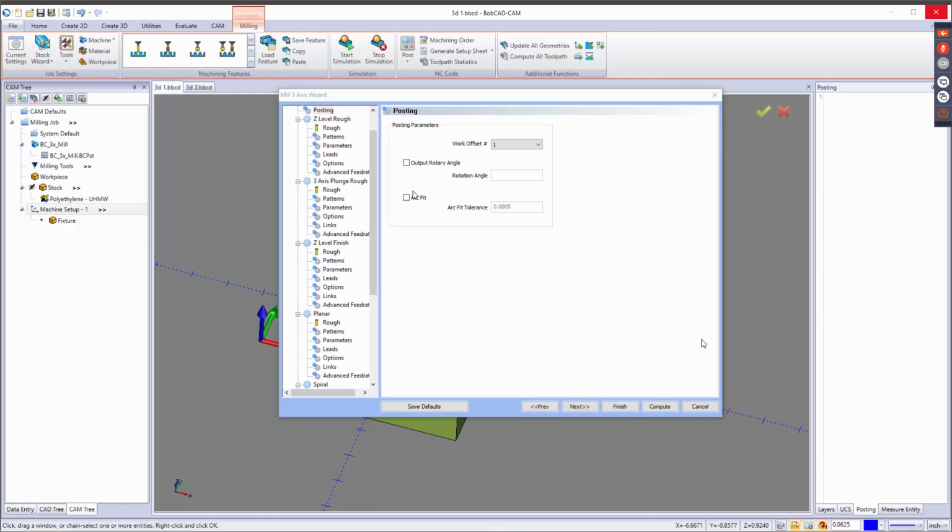And if they don't catch it offhand, going to the toolpath, if it's an older machine, and again, I don't know what to consider an older machine, we'll go with the 80s if you guys remember those or use any of those still. Leave the arc fit off. So instead of an IJK value or an R value in there, it's going to be X, Y, and Z movements. It's going to be just straight line moves. So I will just leave that off for right now. And then from there, we'll go ahead and hit next.